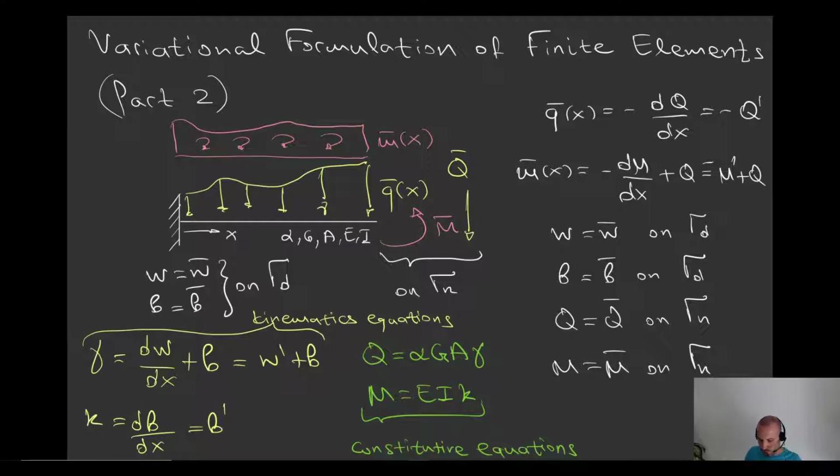Moreover, we also have the constitutive equations, which are indicated here with a green color, and those are with respect to the connection of the reaction transverse shear forces and the shear deformation gamma, and the reaction bending moments M, and their connection to the change in the curvature or curvature itself, kappa.